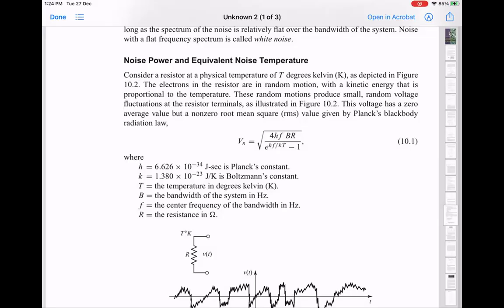And the reason this looks strange is that we are not considering what happens after the amplifier. Usually there is some detector, and that detector now records that information. It could be a spectrum analyzer or it could be a digitizer. And the reason you actually use an amplifier is that the signal levels you have here are incompatible with the detector, because the detector's noise level itself is very high. Which means that this signal is so small that it will be buried in the noise of the detector.